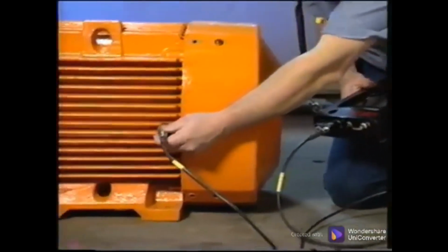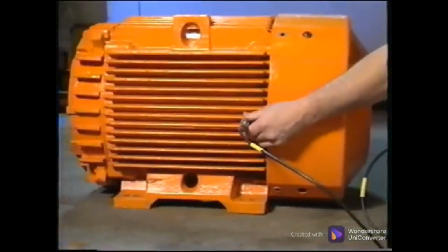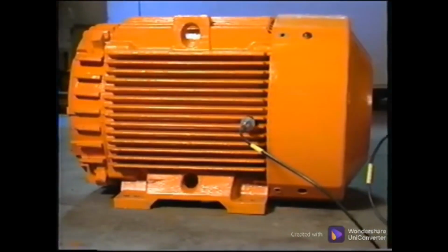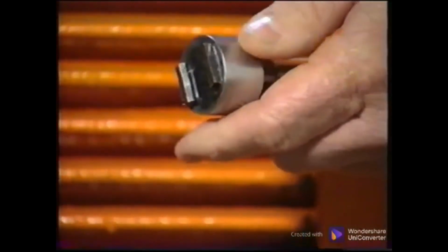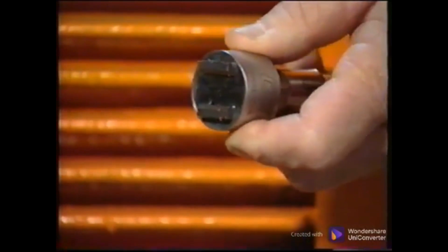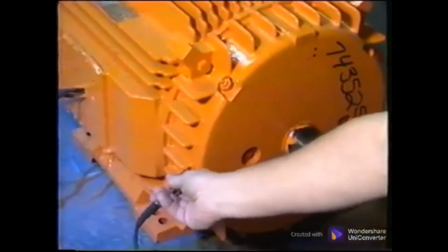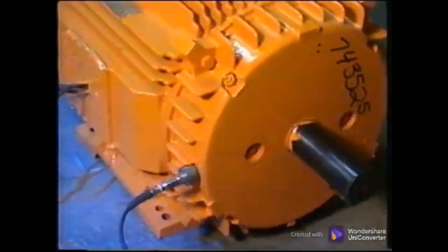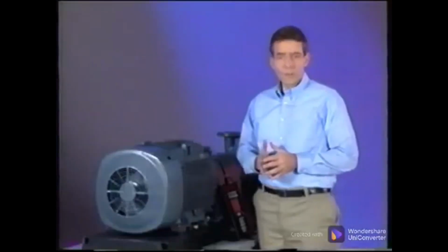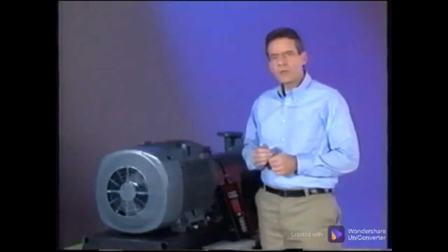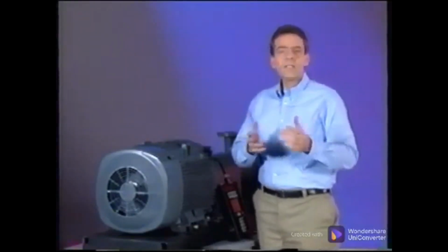The alternative is to collect data through this area of the motor. With these cooling fins spaced closely together, it becomes necessary to place the magnet mount on the fins. It could be placed across the fins or in line with them if the magnet's two poles will line up. Although the horizontal measurement could be made on either side and provide good information, it is best to maintain the same horizontal measurement orientation from one routine survey to the next.